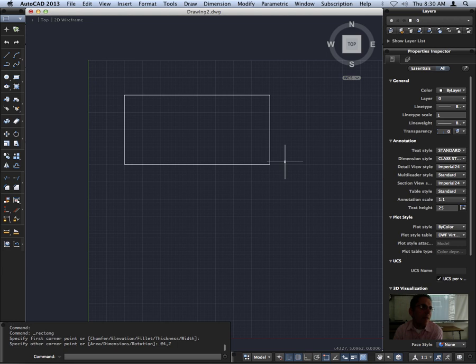So I always recommend manually punching in your dimensions as opposed to using the mouse. As you get into more intricate, precise stuff, sometimes clicking, the numbers look right on the screen, but actually are off. CAD is accurate to 16 decimal points, so the odds of you getting that kind of precision with the mouse are nil.